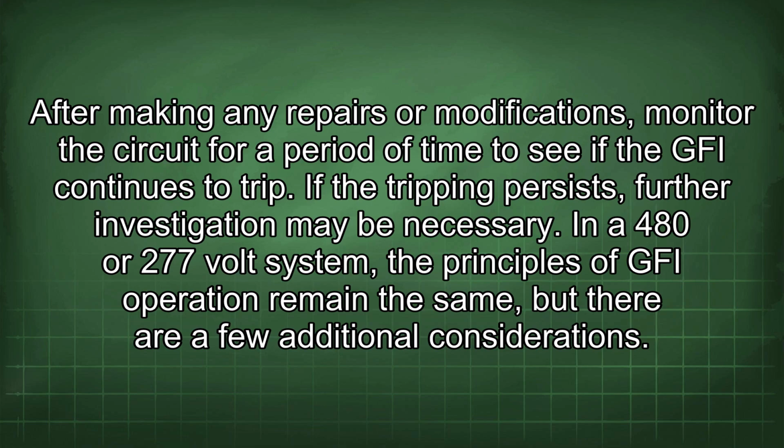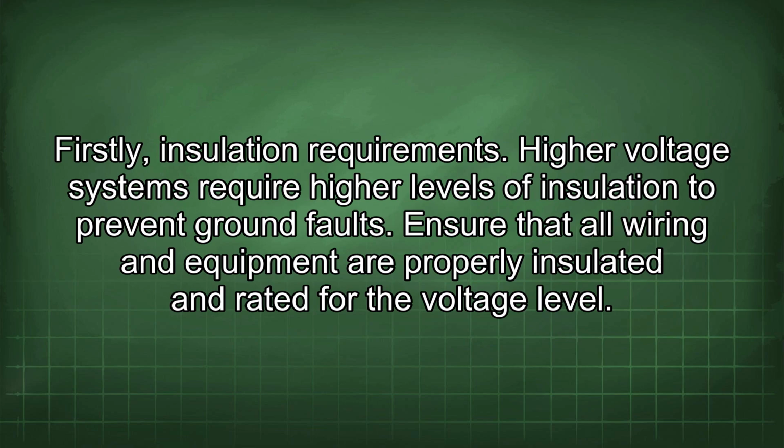In a 480 or 277 volt system, the principles of GFI operation remain the same, but there are a few additional considerations. Firstly, insulation requirements. Higher voltage systems require higher levels of insulation to prevent ground faults. Ensure that all wiring and equipment are properly insulated and rated for the voltage level.